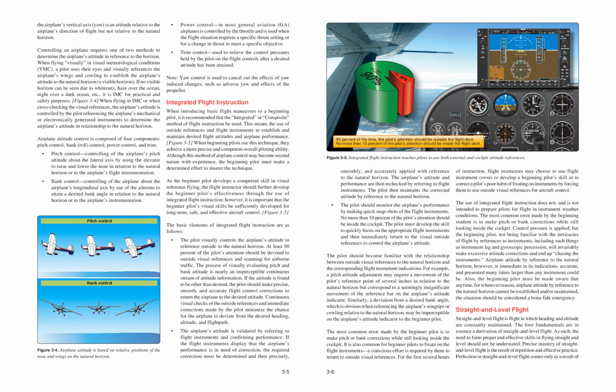Note: yaw control is used to cancel out the effects of yaw-induced changes, such as adverse yaw and effects of the propeller. Integrated flight instruction. When introducing basic flight maneuvers to a beginning pilot, it is recommended that the integrated or composite method of flight instruction be used. This means the use of outside references and flight instruments to establish and maintain desired flight attitudes and airplane performance.